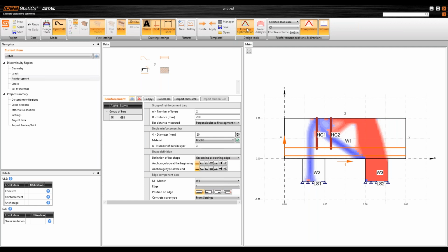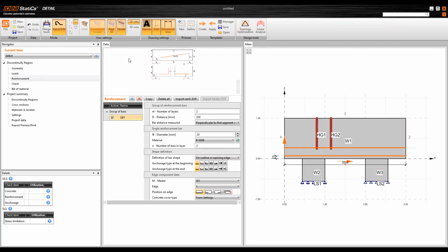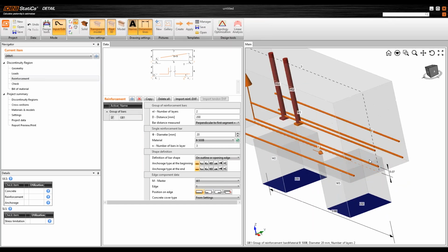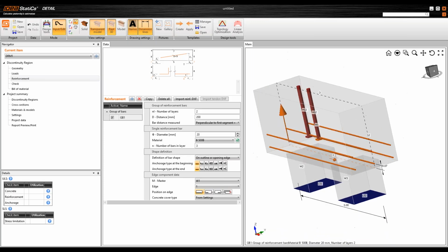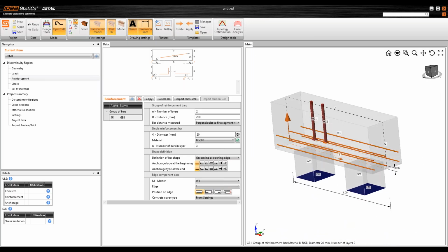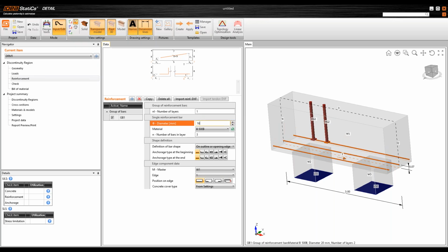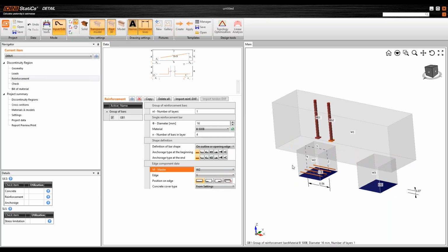If you turn off the topology optimization and switch to the 3D rendering, you will see the real reinforcement, how it looks, how many rebars there are. Yeah, so this is only for your imagination. So there will be one rebar, the diameter will be 16 and 4 rebars in a layer, but I need to relate it to the wall 2, and the number is 4.